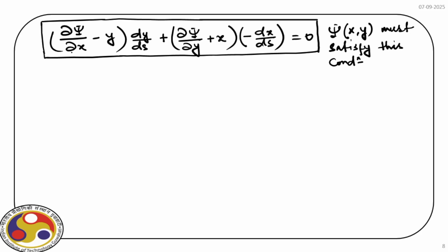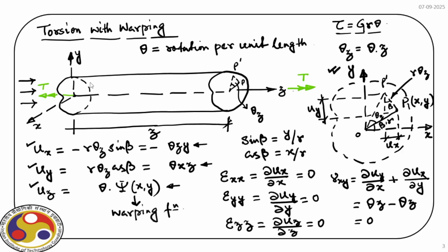Okay. Now let us also find out the force at the section level. So we are at the extreme right face here, and over this face we have only capital T, that is the torque applied. And at the boundary we have identified that fx, fy, fz is 0.